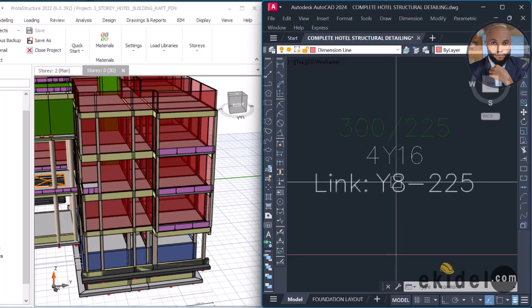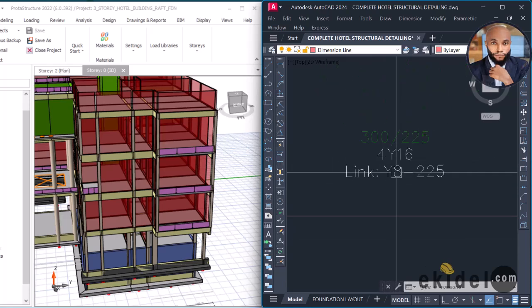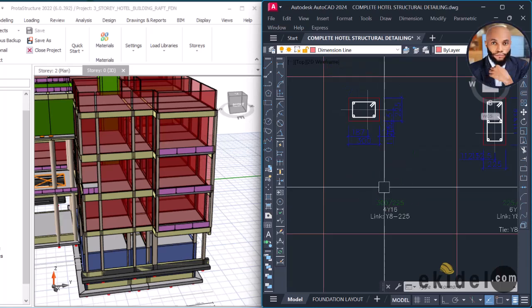But if you are buying from the market, be rest assured that you are buying a lower size than what is stipulated, generally around Africa, most of Africa, but Nigeria, I am sure that happens a lot. So for the safety of that structure, use diameter 10. Okay, I know that, so I will use diameter 10 for this link.